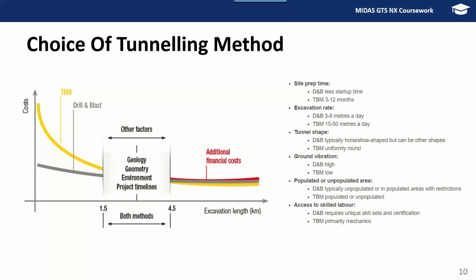And also, one major difference is that drilling and blasting is a cyclic method. So you have to start and then stop, then prep up and then start. But TBM is a continuous method. That is why TBM is much more frequently used nowadays. Also, in DNB, the wall profile is not very uniform. Due to blasting, there might be dislodgement of various rocks or weaker sections of the strata, which is why sometimes we can go ahead with the TBM method, depending on the UCS of the bedrock in there.